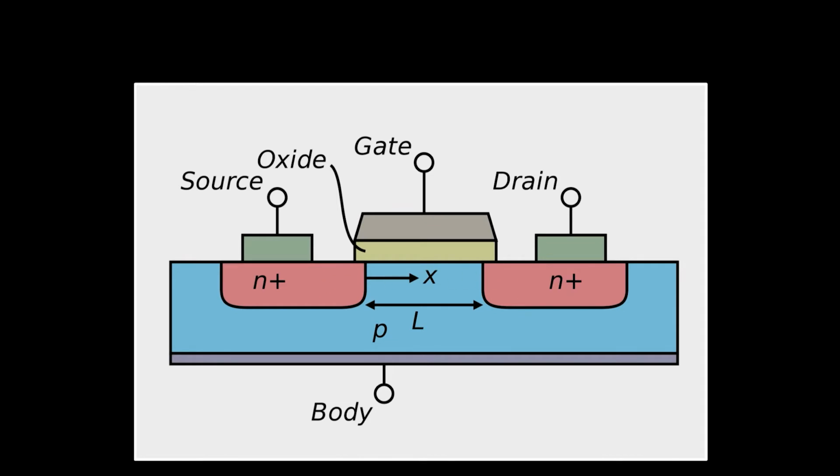Perhaps the easiest way of understanding how a FET works is that the voltage between the gate and the body, also known as the substrate, determines the resistance between the source and the drain. So it's a voltage-controlled resistor. In terms of a water analogy, imagine a piece of pipe connecting the source and the drain. So a short segment of a rubber tube, like a garden hose. The gate to body voltage determines how tightly we are squeezing in the middle of this piece of pipe. If we squeeze the pipe, then no water can get through.